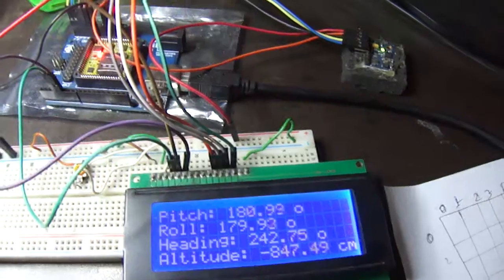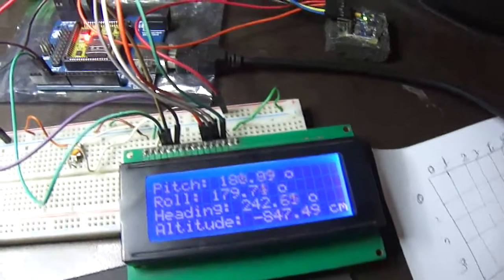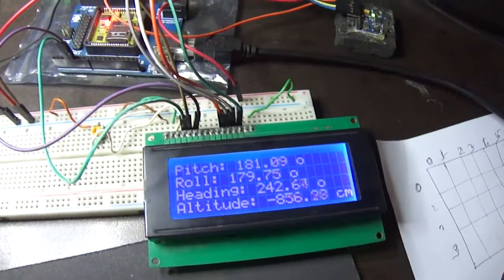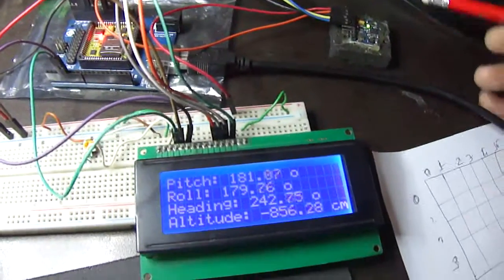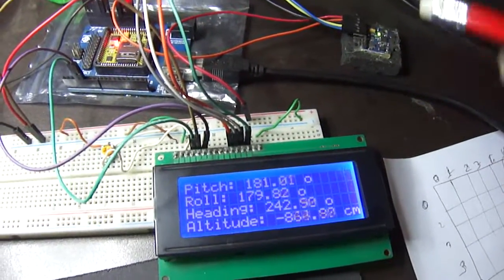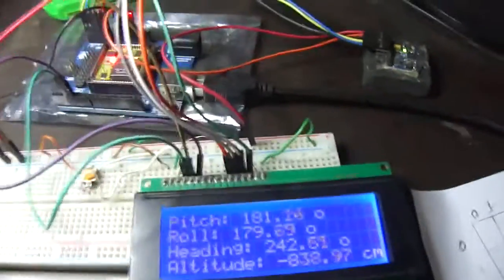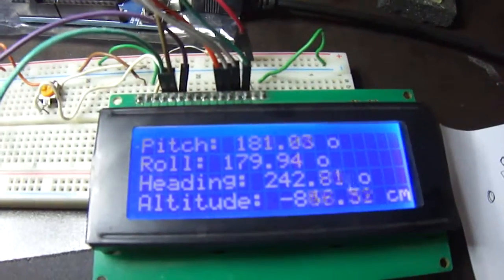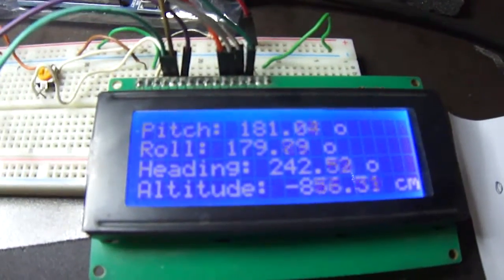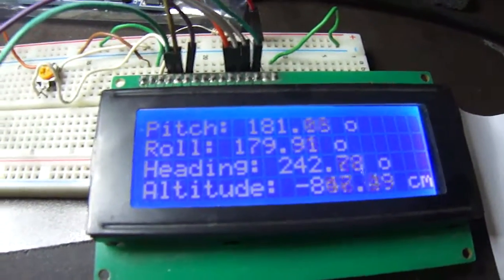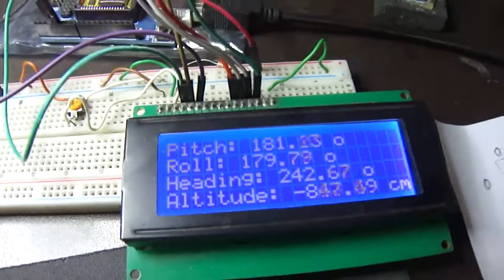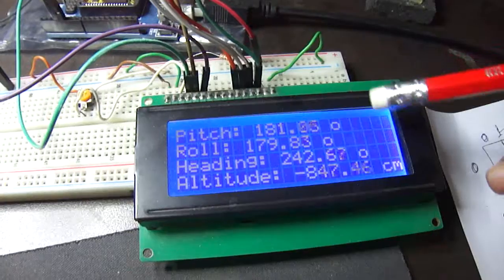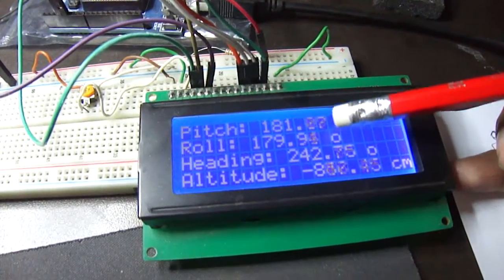I got this sensor for a quadcopter project. It's still going on. The idea is that the quad will use the data of roll, pitch, and heading to find which side it is falling off, and to correct the motor speed so that it can stay level. That means in level condition, the system will try to maintain itself along these two readings.